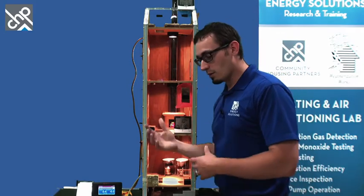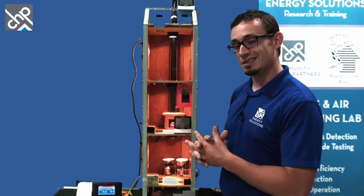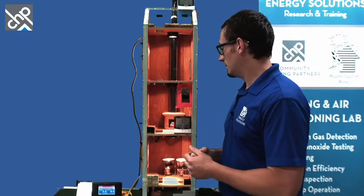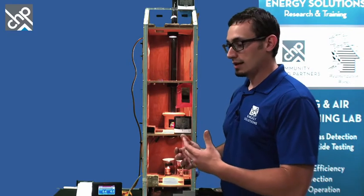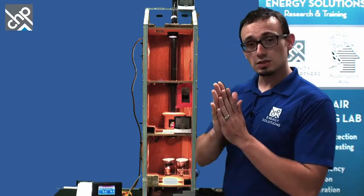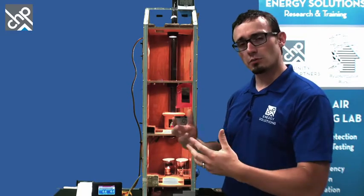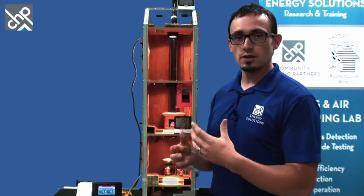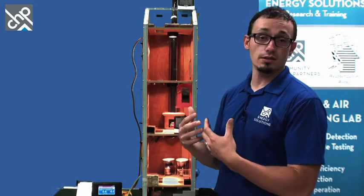If we think about our 3 ways that heat can escape a building or enter a building, the first being conduction. What is true of conduction? Conduction is surface-to-surface contact, so we have to have physical surface-to-surface contact. And in terms of building products, our insulation, our framing materials, those are the kind of things that are going to prevent that heat from escaping in the wintertime or prevent the heat from coming in the summertime.